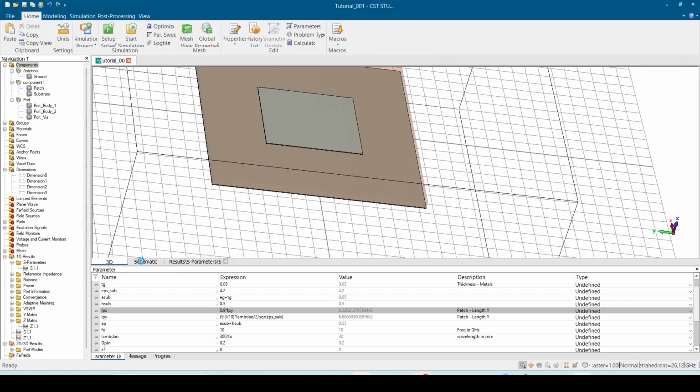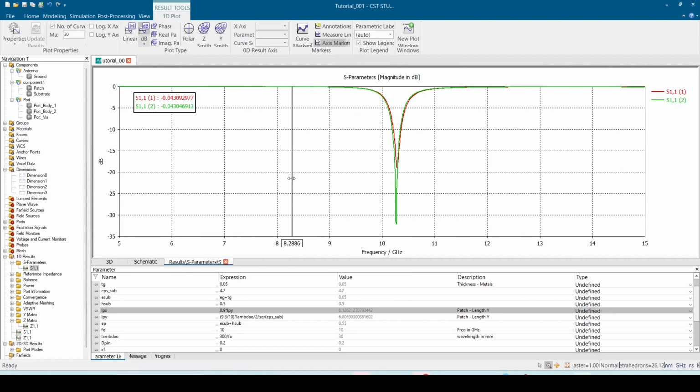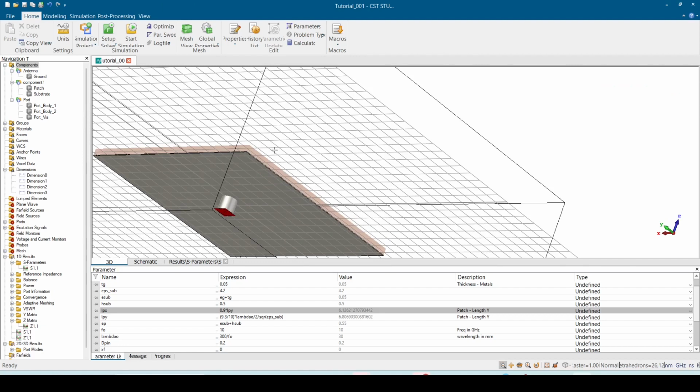So the last thing, of course, because it will not be something very analytical: if you want to do this step, you have to do the last frequency scaling. This is why I'm saying that I like to link everything in the same way, because everything is depending on the relative distance and the relative location and the relative dimensions. The only thing that can really make it different is the feeding mechanism. I don't scale the ports with it. For example, if I scale everything, I don't scale the ports.